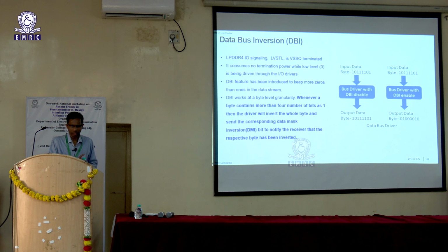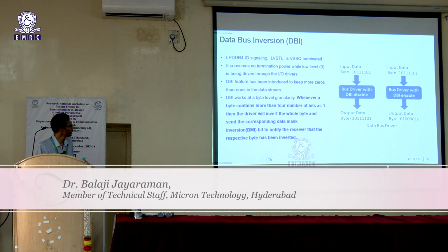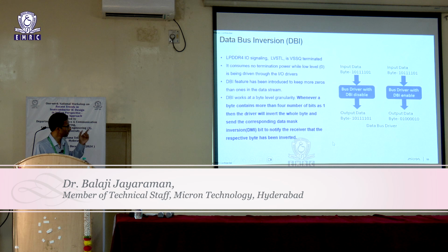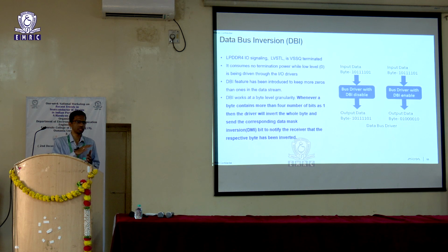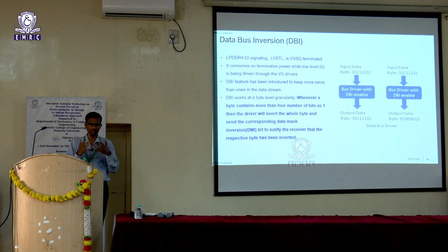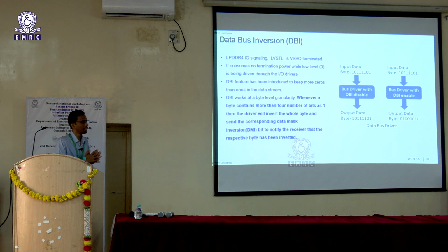And data bus inversion. So, this is again a low power feature. So, if you are transferring bits, ours is the LP, a VSS terminator logic. So, when you say VSS terminator logic, when you are transferring a 0, you actually do not burn power, and when you are transferring a 1, you will have a voltage divider, and that is when you burn power. So, if you are transferring a stream of zeros, there is nothing on the VDDQ that you are burning. It is actually idle, I would say.